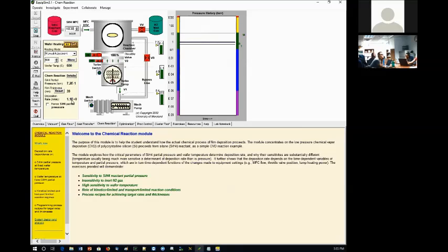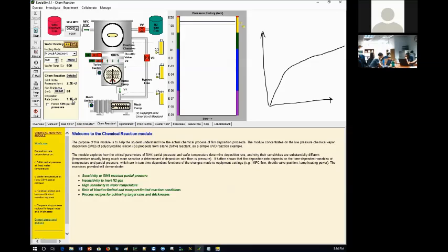I end up with 1.1, okay? So if I add one more zero just for the sake of doing it, I don't increase it. You guys see that? So it's getting stuck. I have increased it very much. It's almost close to the venting 760, you see? But it's stuck. What does that mean? Now I'm working it into the chemistry dominated region because I'm supplying too much of gas, but it's not increasing the deposition rate. So I started like this, and then all of a sudden I saturated and I stayed there.